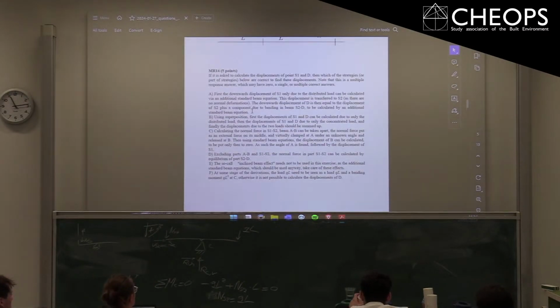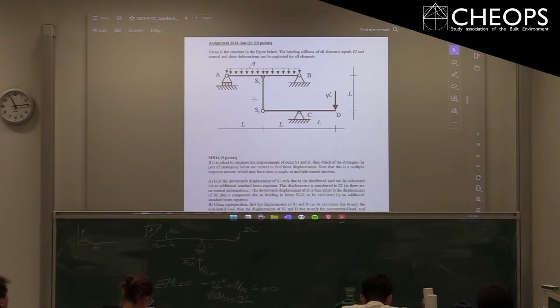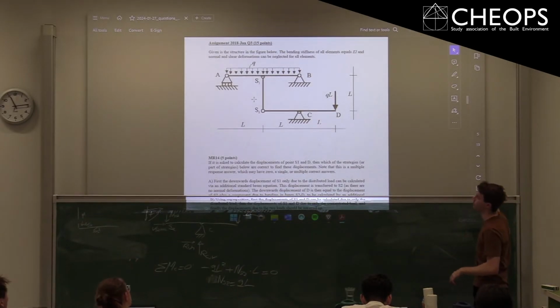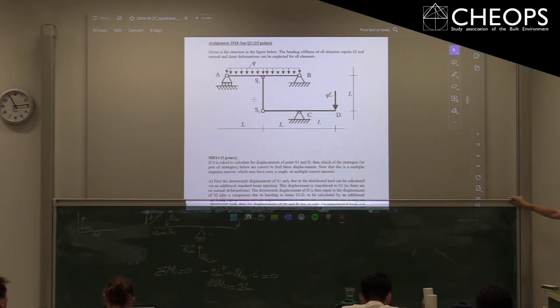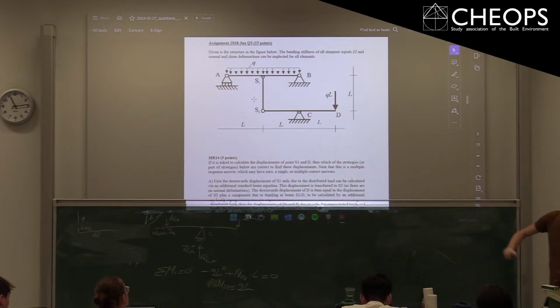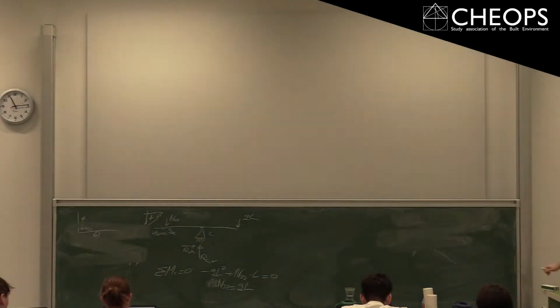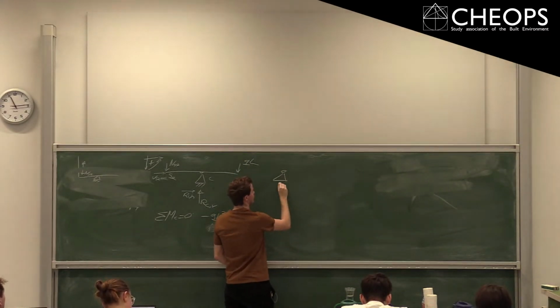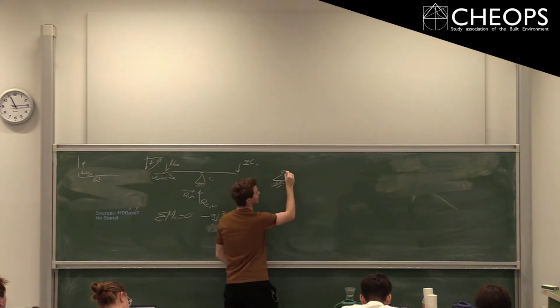And then we go back to this multiple response over here, why that point A was incorrect. So if we have that structure, we want to know the downwards displacement. And as you can see, A to B is actually one of your standard beams. It's just a simply supported beam. So we're going to draw now a free body diagram of that part of your structure, where you've got the hinge on one side and it goes to there.